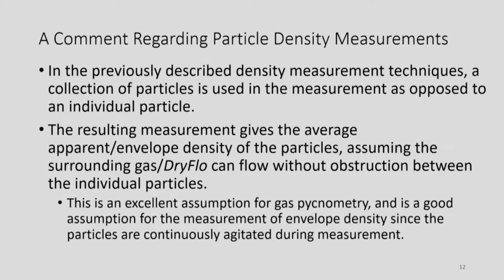Again, we talked about particle density, right? Though we are trying to characterize particle density, we are using bulk powders. We are not using one particle. For example, if you're using gas pycnometry, you will take like 50 gram, 100 gram of powder and then measure the density. Since for small particles, getting particle-level density is challenging, we use this bulk powder method and try to get the individual particle densities from there. So it's kind of correlating the bulk properties of the powder to the individual particle-level property.